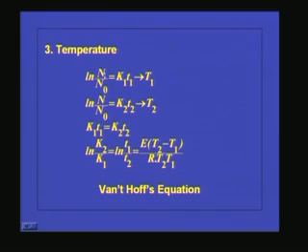Now, we will see how the temperature effect comes into disinfection, because we know that as the temperature increases, the activation energy of the reaction also will increase. So the rate of disinfection will be changing, increasing with increase in temperature. This equation shows that ln n by n naught, where n is the number of microorganisms present at any time t, and n naught is the number of microorganisms present when t is equal to 0, that means before the disinfection, we can write like this: K1 into T1, where K1 is the constant and T1 is the time, at a temperature T1 degree Kelvin, and the same is written here for a temperature T2. So the rate constant is changing and contact time is changing, but we know that in both cases this term is the same.